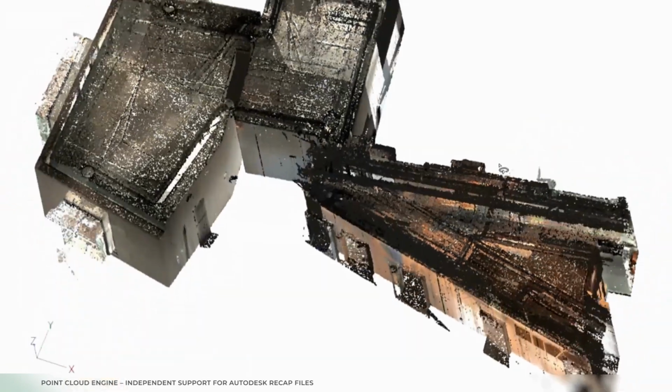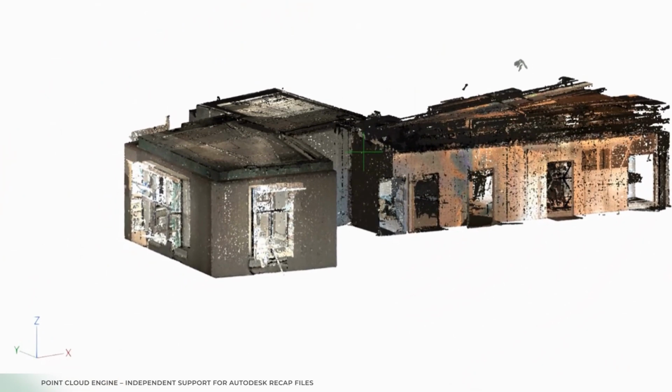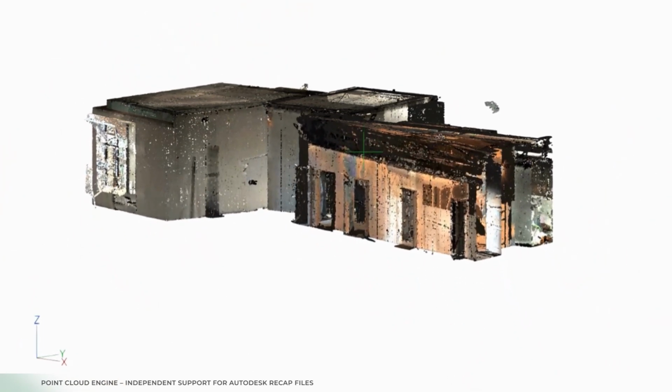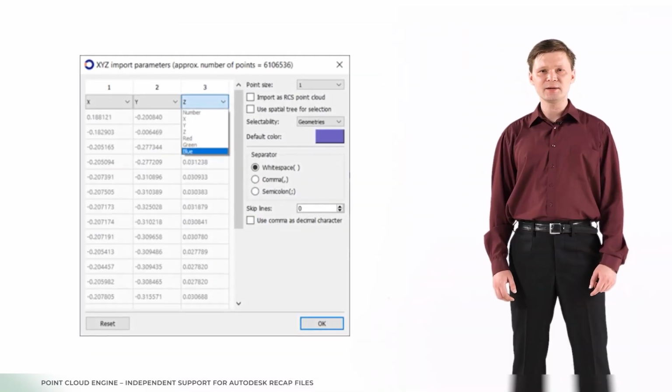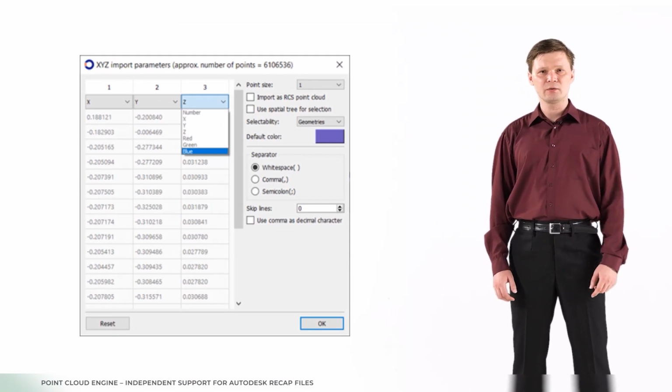For example, if you open a PTS file in ODA Viewer, your PTS file will be converted to a structured RCS file and efficiently rendered using our base engine. ODA Viewer will similarly import and convert the XYZ point cloud format, which has no strict description, so it's not a simple task to process all data cases automatically for this format. Our sample application contains an additional dialog, which allows the user to guide the conversion process.